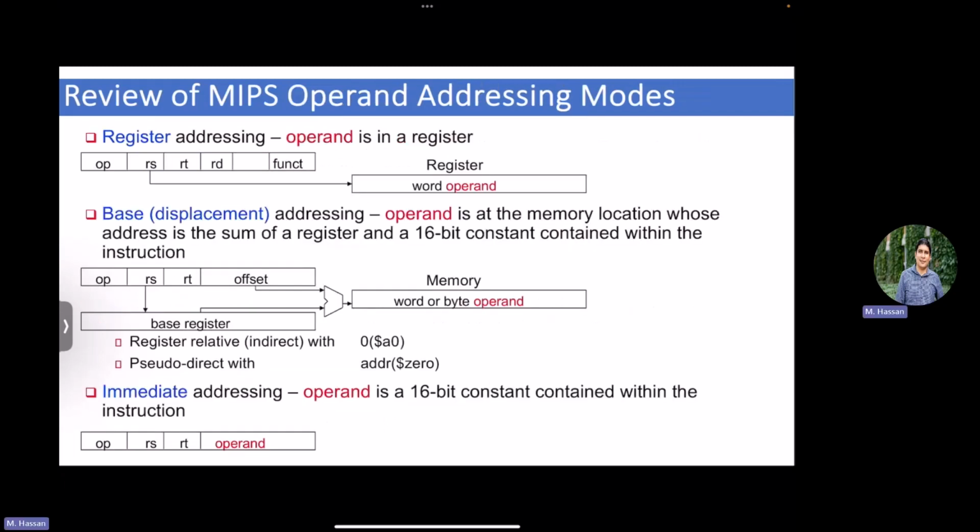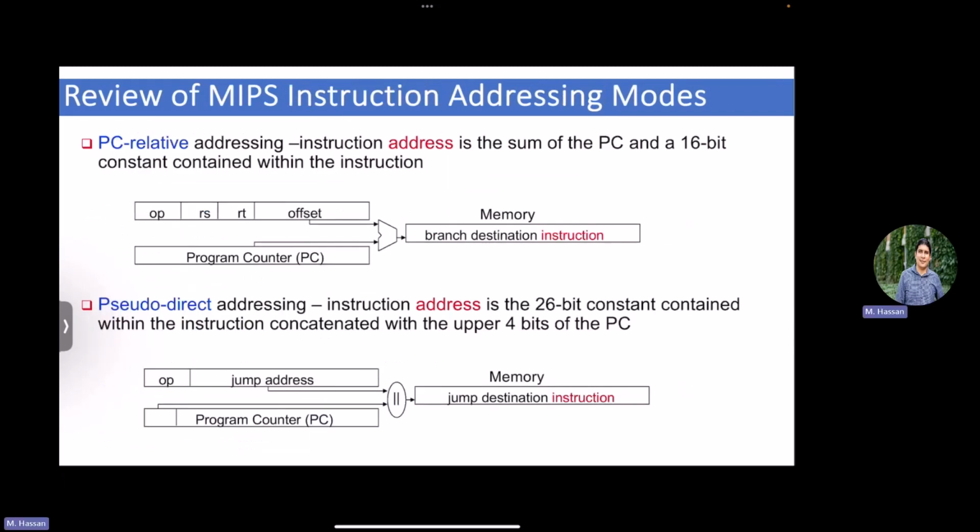So this base displacement is simply a special case of the program counter relative displacement, as we were saying in the conditional branch instruction. And then we have something that we called yesterday a direct jump. But in fact, it's not fully direct, because if you remember the jump format, the width of the jump address is 24 bits. It cannot be 32.